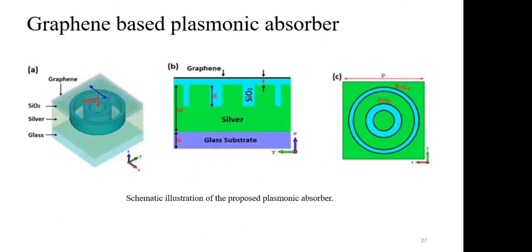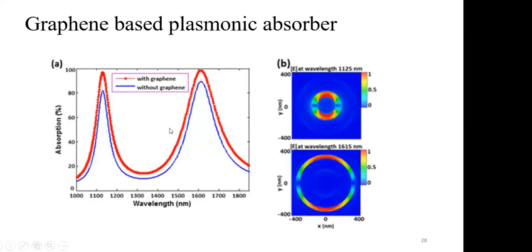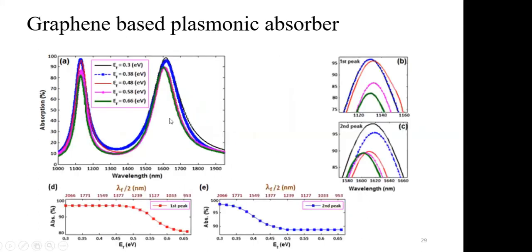It is the same design, but it was not elliptical. We wanted to test it on two resonators which are separated in the design. And as you see here, again we have two peaks which by graphene can be tunable. But again, the interesting thing is not the jump in absorption. The interesting thing was each peak can be tuned separately again, and on another frequency we observe the same results. So it shows us that by plasmonics we can tune different types of resonator on only one structure.